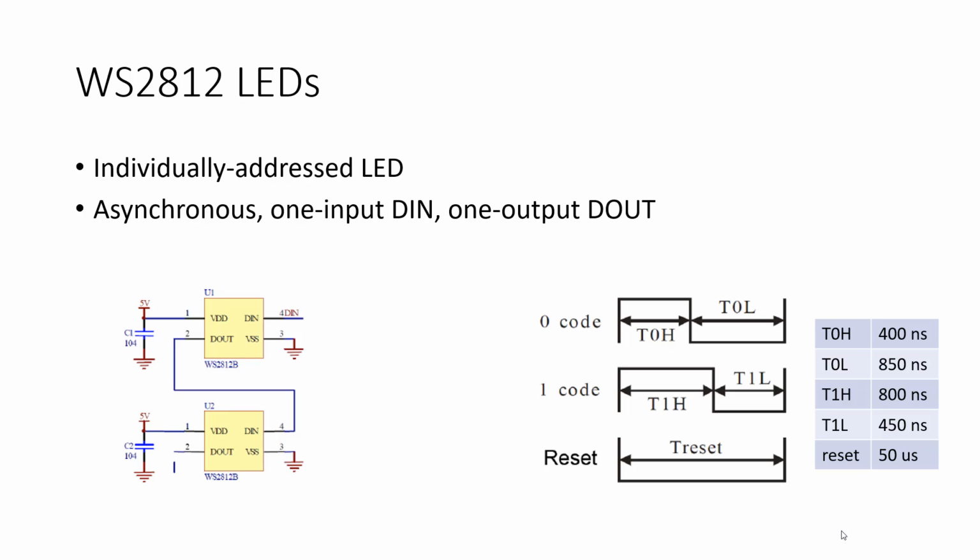And then the LED recognizes those based on the time that the signal is high and the time that it's low. If you screw up and violate these timings, like I said earlier, if you have 400 high, 400 low, then I don't know what it does. Probably it just doesn't do anything. Probably just ignores that, I would imagine. I haven't tried that, but the idea is that you want to stick to these two shapes.